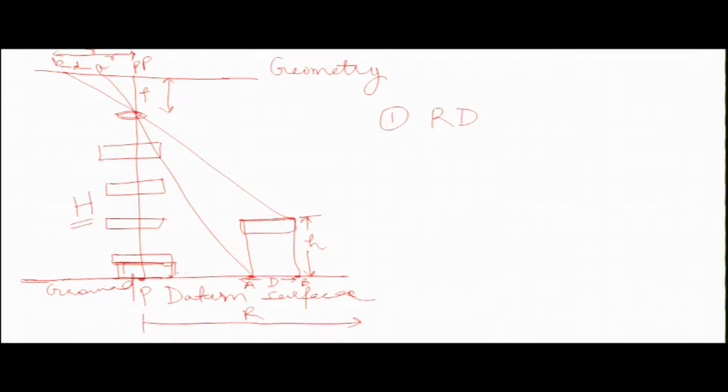So what it means, that when an object or a building is located away from this point, the relief displacement will be more. So this building is represented over your photograph here like this, point A to B, because photograph is a two-dimensional plane. So you can see this building, but in a different manner. You will see your building like this. So it will be covering some of the area over the photograph. Okay.